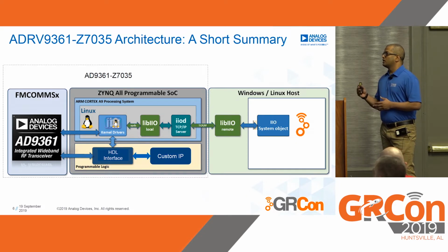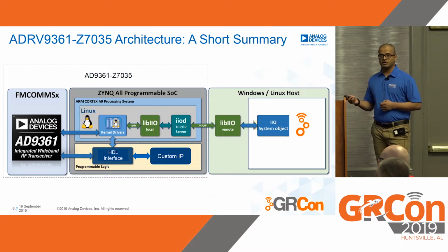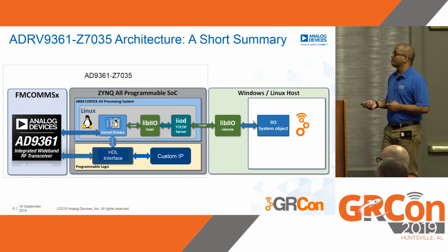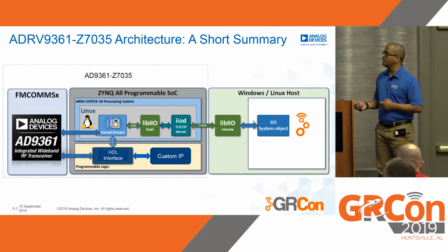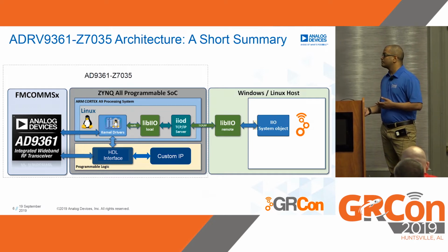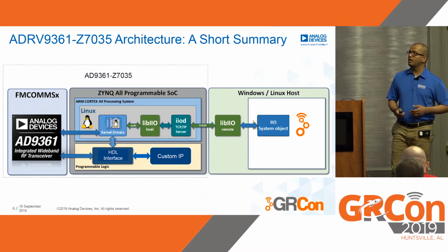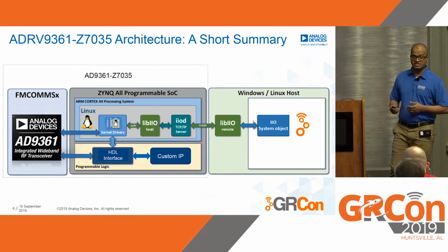So to talk a little bit more about the architecture of the RF SOM, my colleagues have gone into more details regarding this slide, this architecture, but I'll spend a few minutes. Whether it is FMCOMMS or Pluto SDR or the RF SOM, the architecture is pretty similar. You have the transceiver here, which communicates with the kernel drivers in the embedded Linux on the ARM. You have libIIO that is talking to the transceiver as well as to the host application in order to configure the transceiver and perhaps capture data and perform signal processing, etc. The kernel drivers also talk to the AD9361 HDL IP, and perhaps there is some custom IP that is also able to do the signal processing on the samples received.